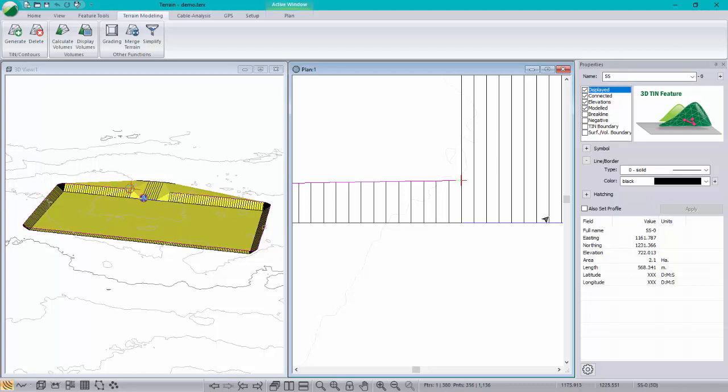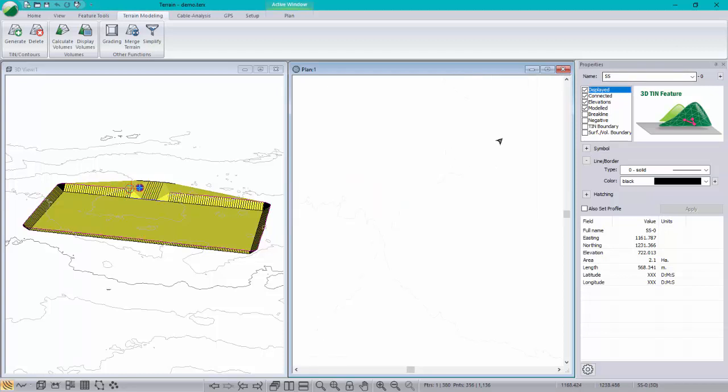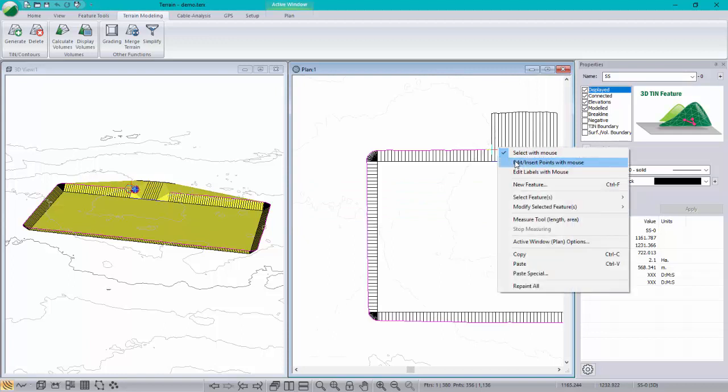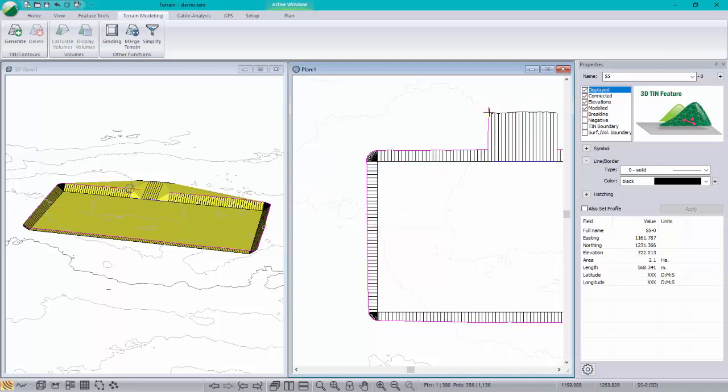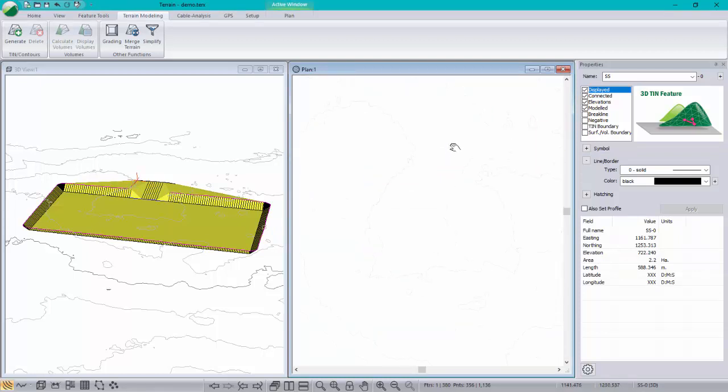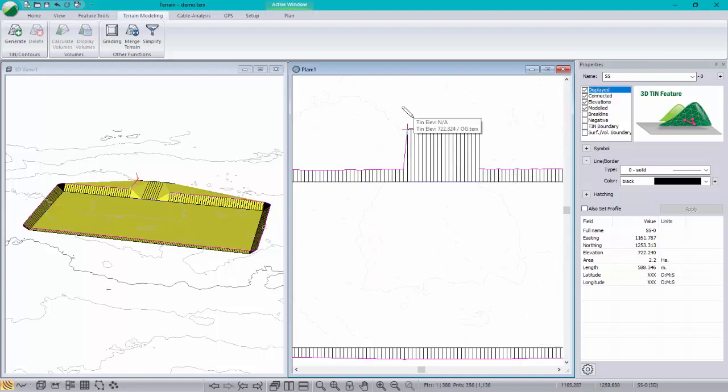So I want to take this feature, this one, sorry, right here, called SS, and snap it onto the end of the other feature. I've now connected the SS from both of our grading operations together. So with them both selected, we just hit Control J, we've joined it, and let's do that on the other side of our ramp here too.